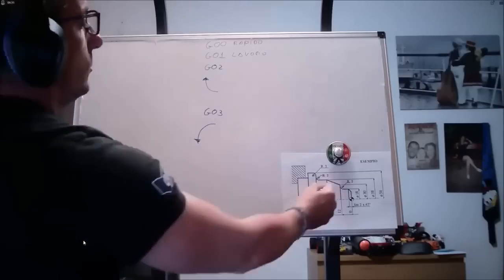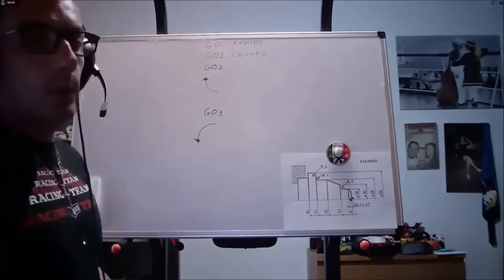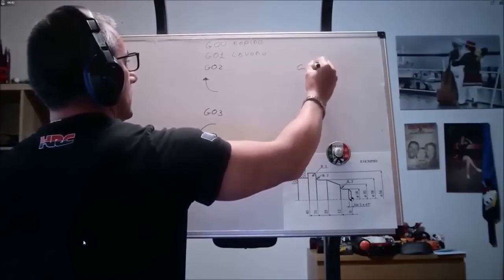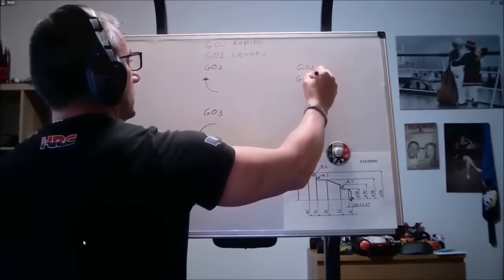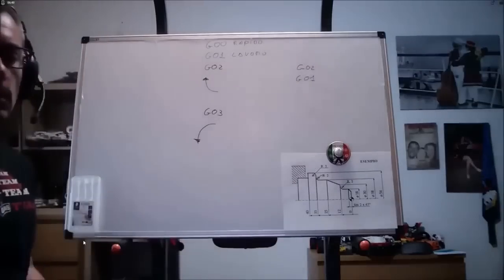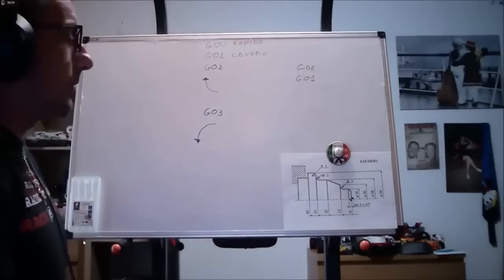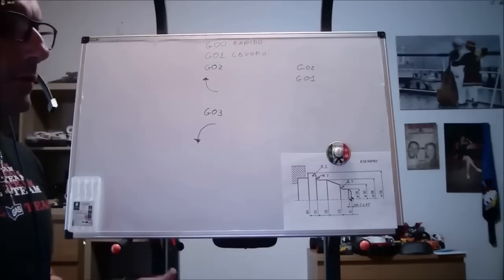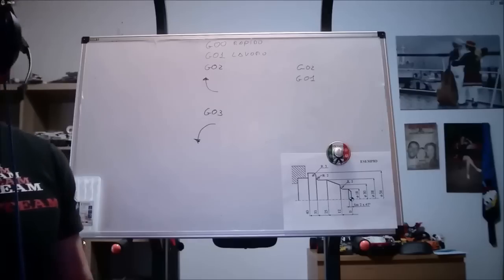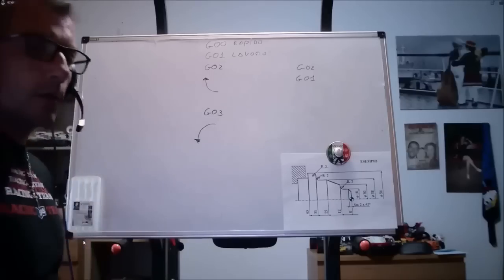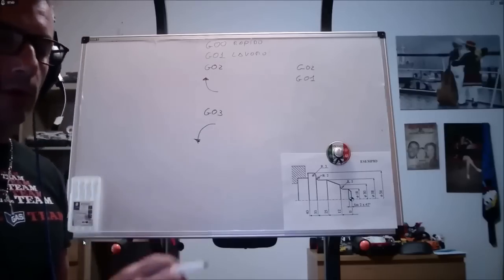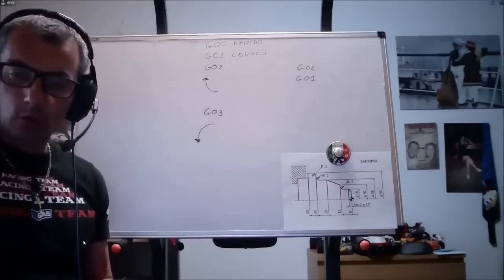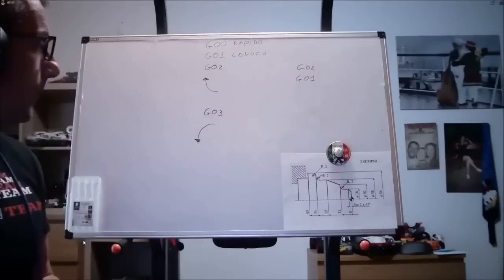If I have a linear interpolation movement between two lines, I must always write G01 after G02. Otherwise, the machine will require a new circular interpolation. Remember, it is not self-excluding. So, G02 and G03 must be followed by a corresponding G01, G02, or G03, depending on whether I continue to make a circle or start another linear movement.